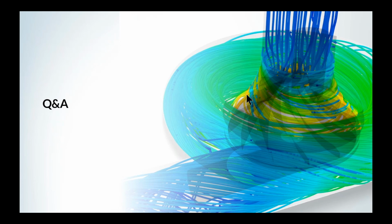For users around the world, for users in different departments, different disciplines, whether it's structural, whether it's fluids. And this proprietary technology that we've invested in allows just that, where you don't have to worry about that Y+. The meshing is automated. Of course, you have controls, right? And you'll need from time to time, case dependent, to update the mesh refinement.